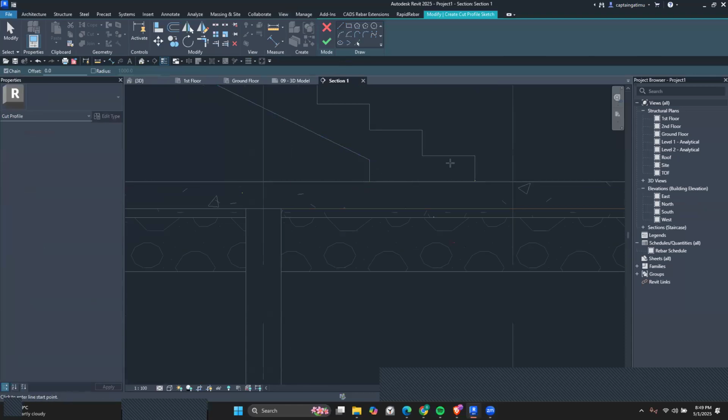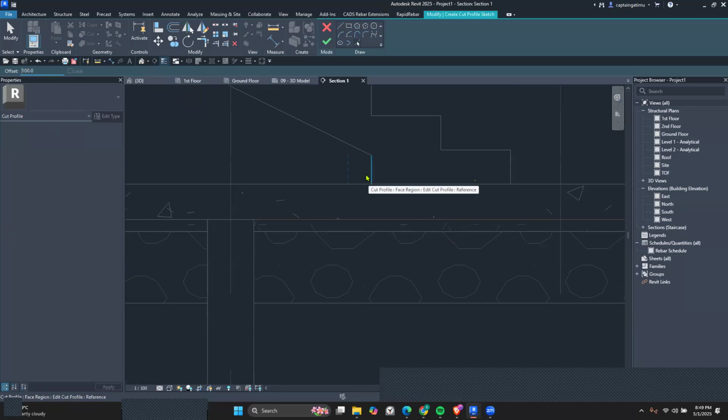We want this thickener to be about 800 millimeters thick. So let's do that. I'm going to use this as a guide. This part here is 600 millimeters thick. To make it 800, I need to offset this line by 100 and this line by 100. These two lines will be quite useless. They are just here to guide me as I continue to create this thickener.